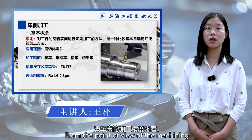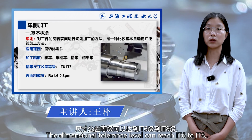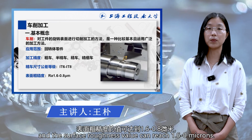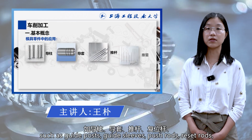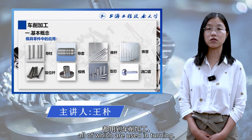From the point of view of the machining accuracy of the lathe, turning can be divided into rough turning, semi-fine turning, and fine turning. The dimensional tolerance level can reach IT6 to IT8, and the surface roughness value can reach 1.6 to 0.8 microns. There are many rotary parts in the mold, such as guide posts, guide sleeves, push rods, reset rods, die handles, and cores, all of which are made by turning.